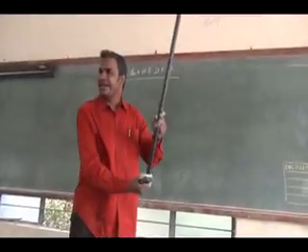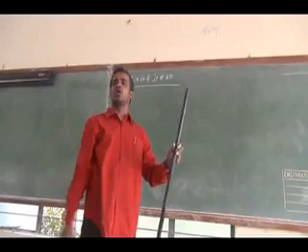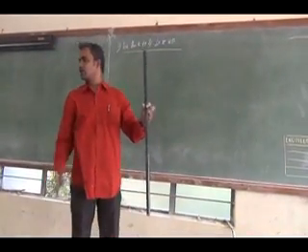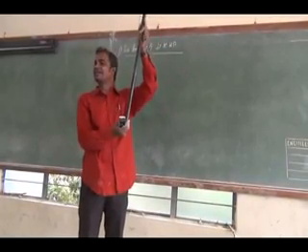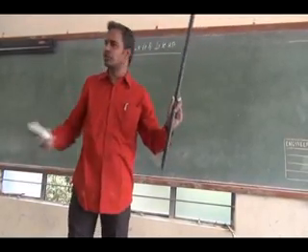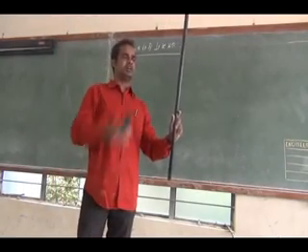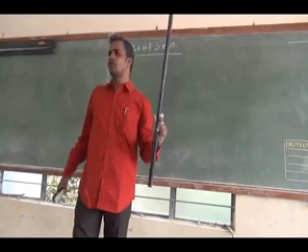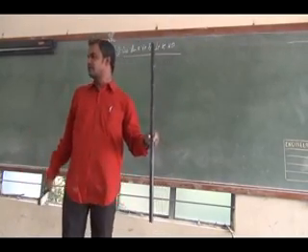Okay, that is another case, right? The one end's position will be given, the line length will be given, and the line orientation will be given in your problem, whether it is parallel, perpendicular, or inclined. Since it is in the first quadrant, it will be above HP and in front of VP, and the distance of one end will be given, right? So you are asked to draw the projections of the line.